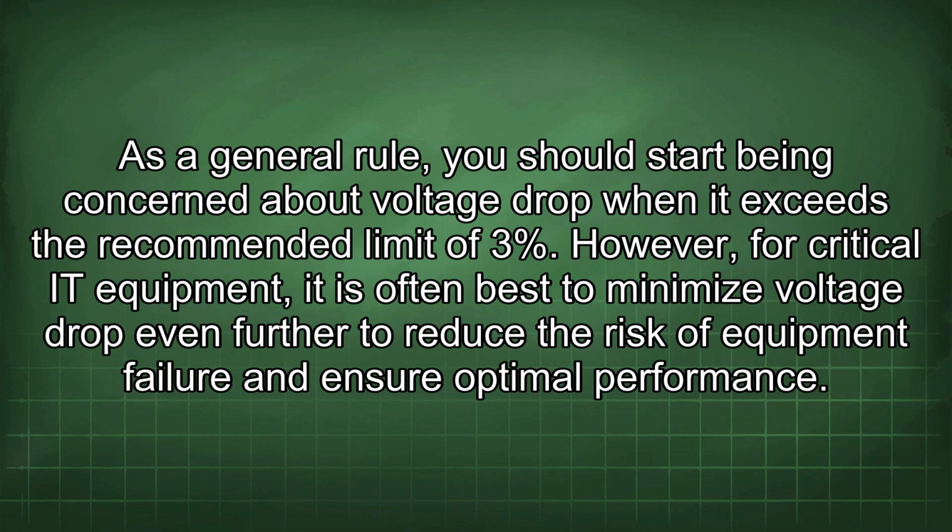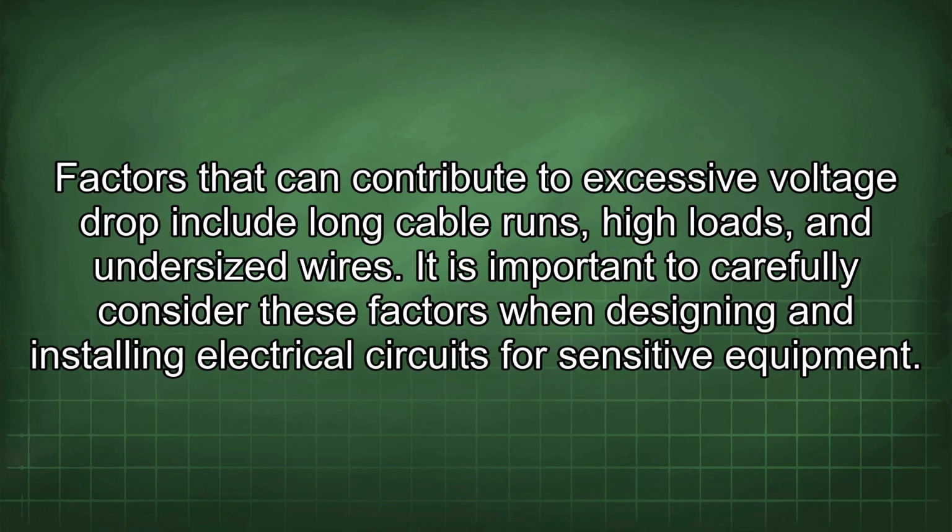As a general rule, you should start being concerned about voltage drop when it exceeds the recommended limit of 3%. However, for critical IT equipment, it is often best to minimize voltage drop even further to reduce the risk of equipment failure and ensure optimal performance. Factors that can contribute to excessive voltage drop include long cable runs, high loads, and undersized wires. It is important to carefully consider these factors when designing and installing electrical circuits for sensitive equipment.